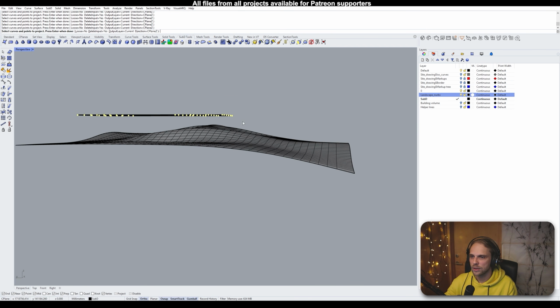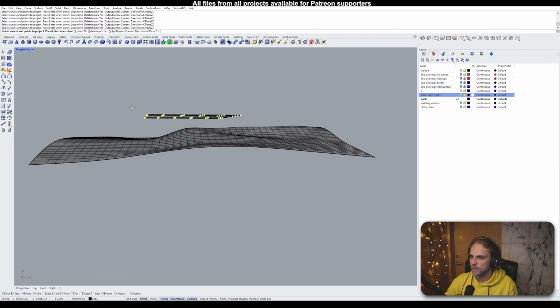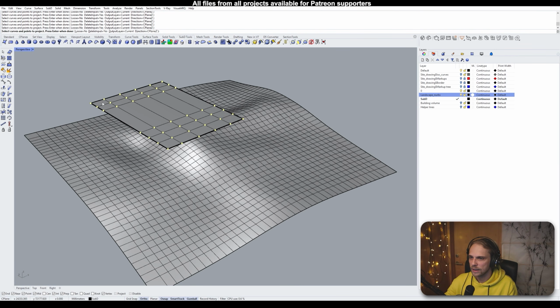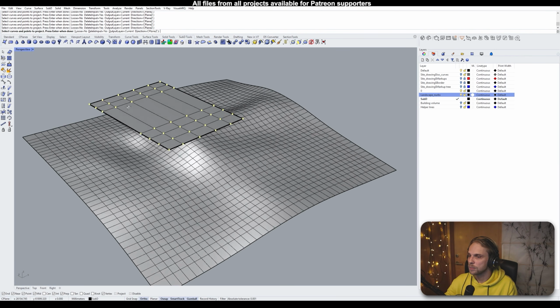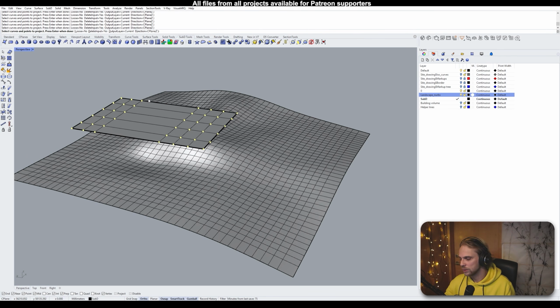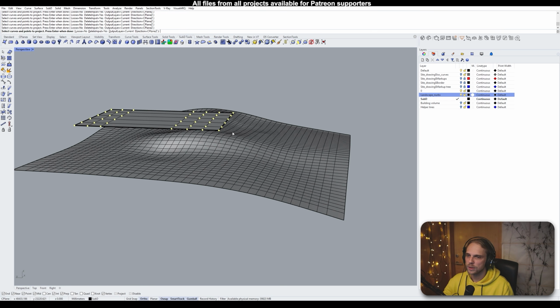If I just drag around the subd form like that, then it catches all of the points. So that's one way of how you can do it. Another way would be to hit F10 and then type in cell PT, but this one works, so we use it. So we have these points that are going to be projected. I'm happy with it, and I'll just hit enter.